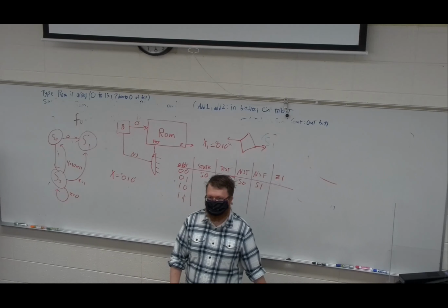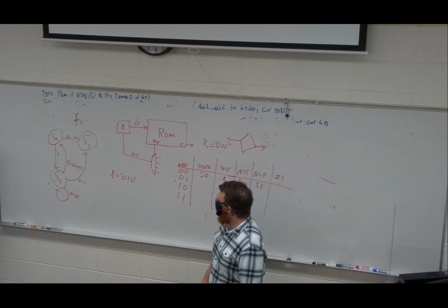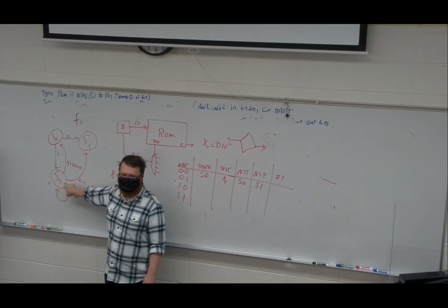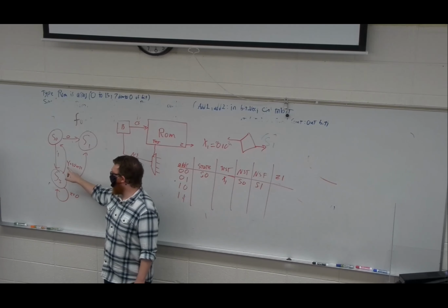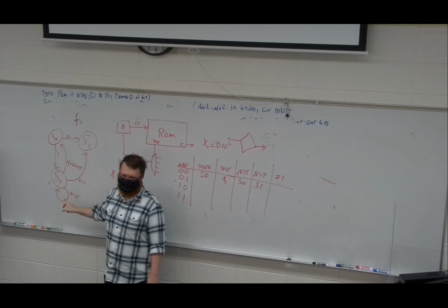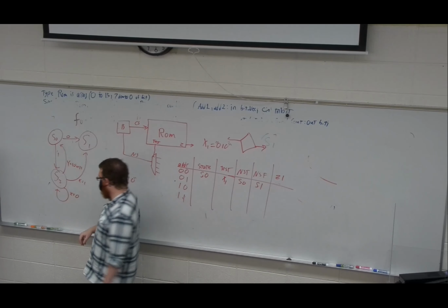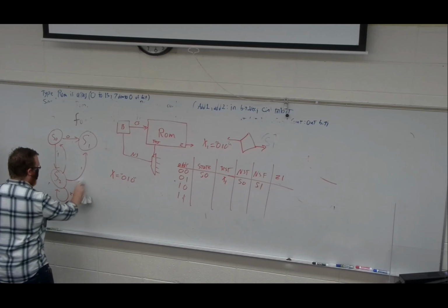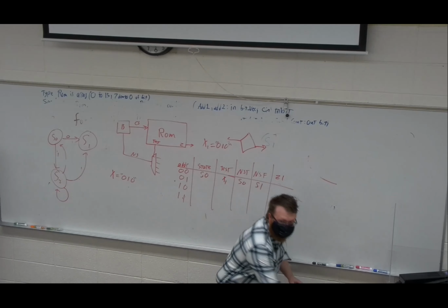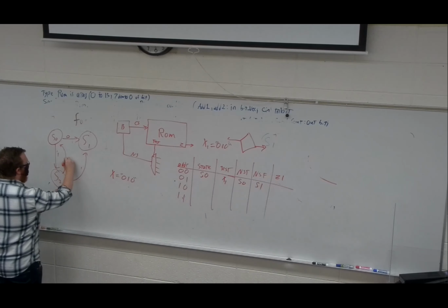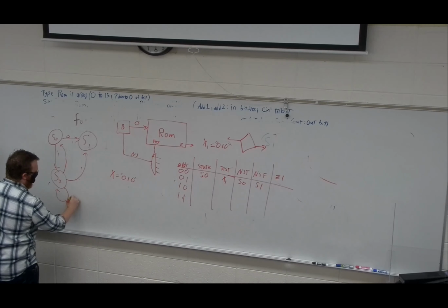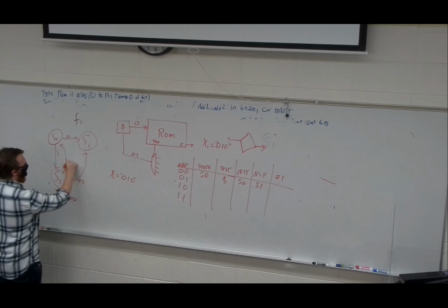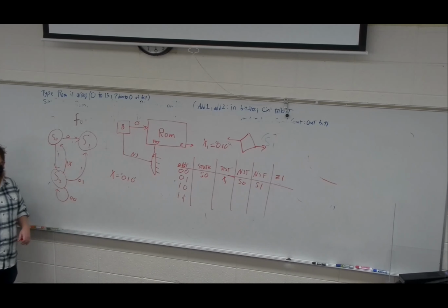How would you turn that into microcode? You just have to add 1 additional state. So your first test would be it. If I'm assuming that if y is 1, I go back to 0 regardless of what x is doing, I would specify that. So let me redraw those numbers so that it's clear. Using the format x comma y, it would be 0,0; 0,1; and 1, don't care.